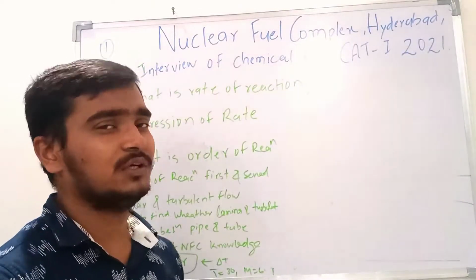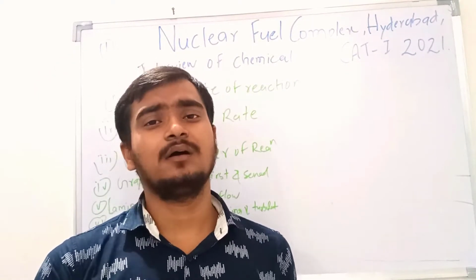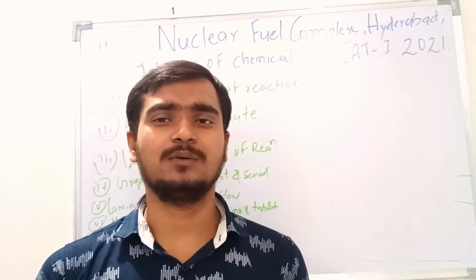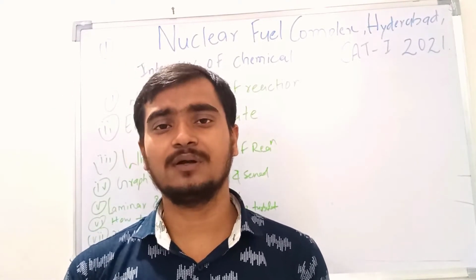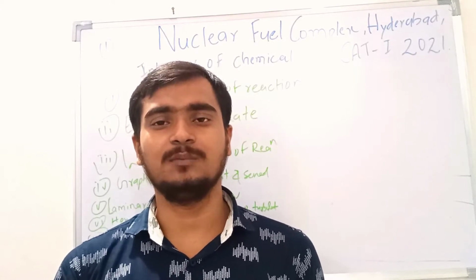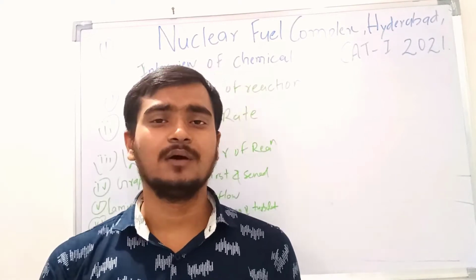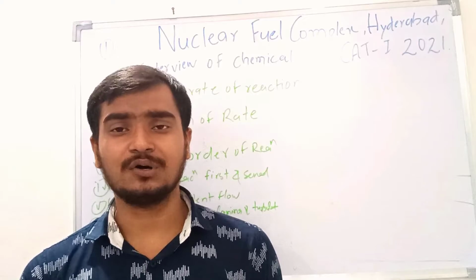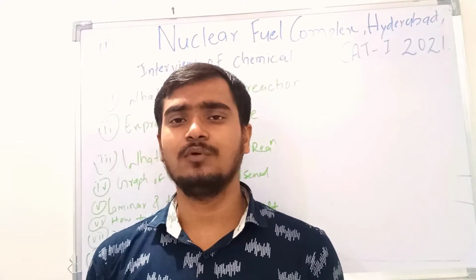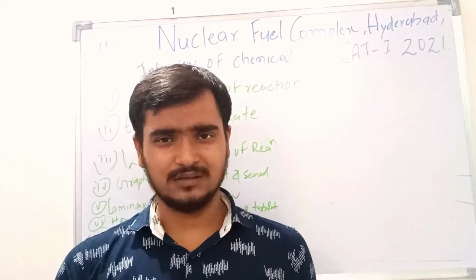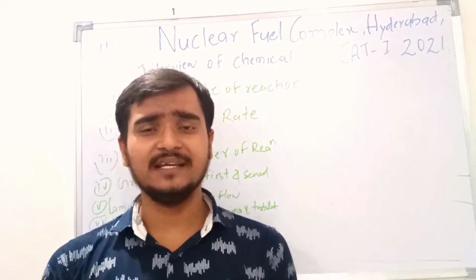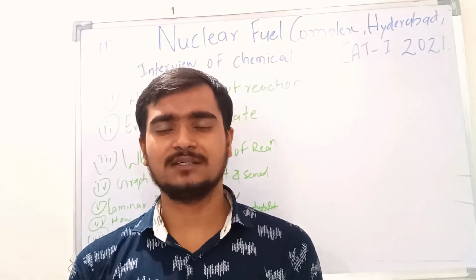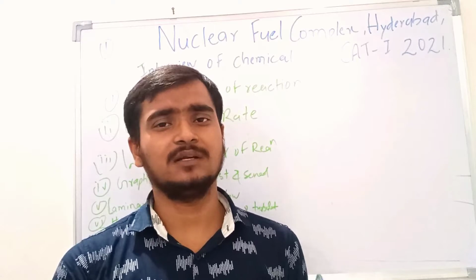Then they ask how you can find whether the flow is laminar or turbulent. With the help of the Reynolds number, you can easily find it. If the Reynolds number is less than 2100, it is laminar, and if it is more than 4000, it is turbulent flow. In the laboratory, you can also use Reynolds' experiment to find whether it is laminar or turbulent.